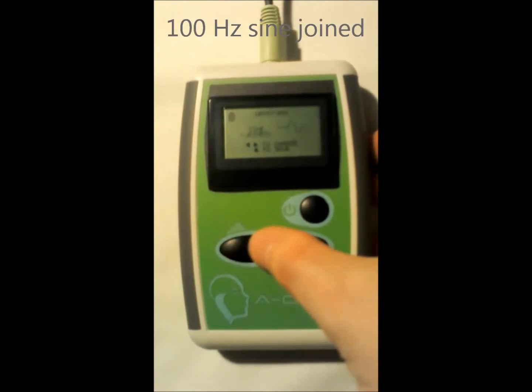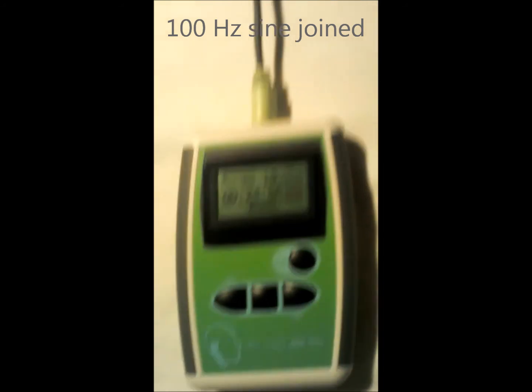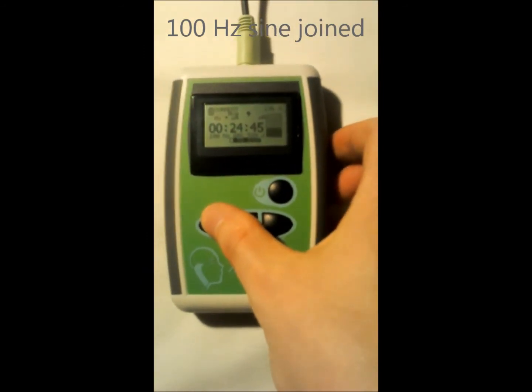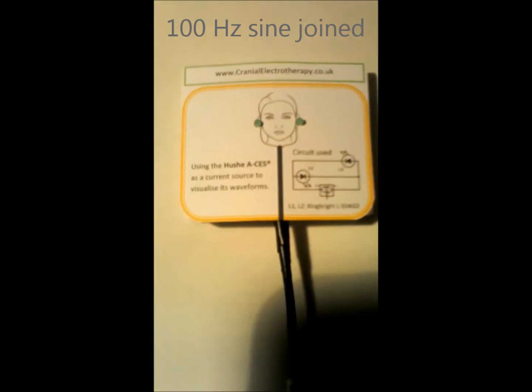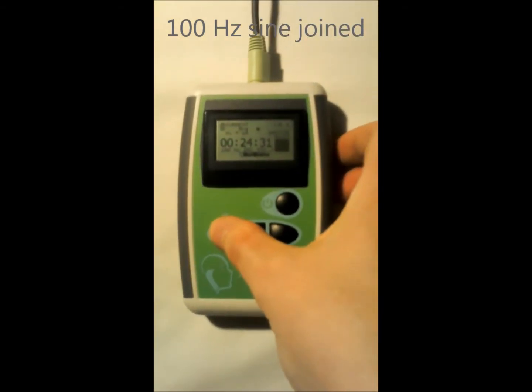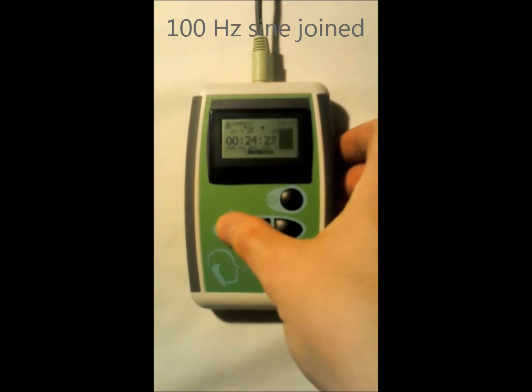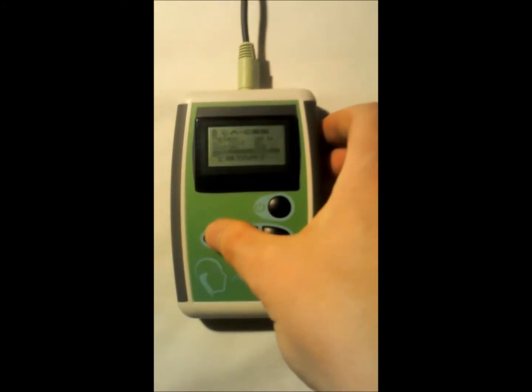I'm now changing the waveform to a sine joined type, which should result in less energy and a dimmer glow in the LEDs. At level 1 there's nothing much to see again. Level 5, the LEDs are glowing, but less than they were with the square wave. And at maximum level the LEDs are glowing brighter, but not so bright as they were with the square wave.